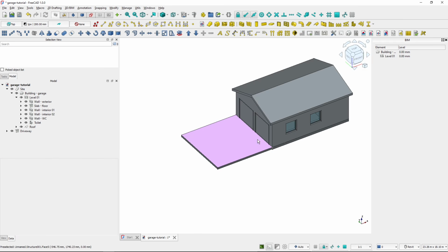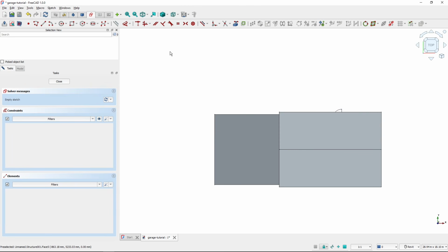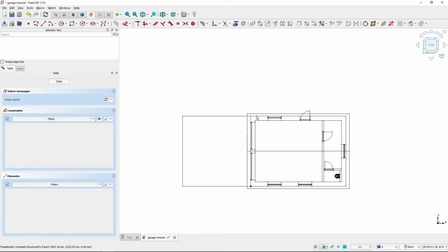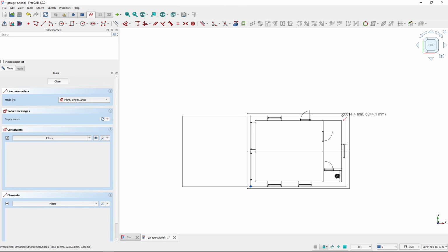And now to make the grass, I will again create a separate sketch, so I will fire up the sketch tool, and I will change the draw mode to wireframe, because now I will want to make a grass plane like this, but I will want to snap to existing geometry. And you can see that when I'm in the sketch, I cannot snap to anything else, unlike when I'm using the draft tools, only this first point.